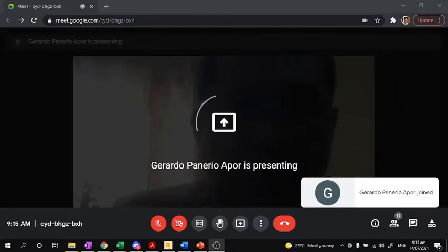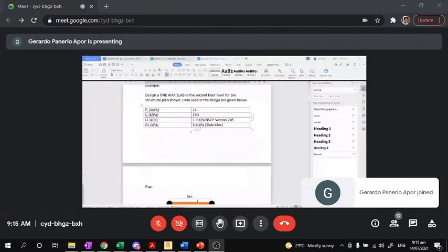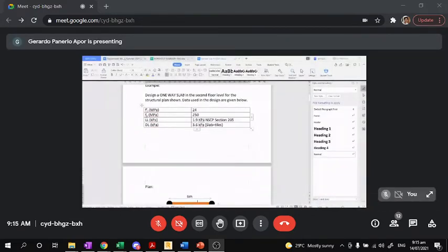In this plan that we are going to design, the live load is 1.9 kilopascal. Remember, kilopascal, so it should be per area. The dead load is the weight of the floor, which we assume to be 5 inches, plus the thin tiles. So, it is 3.6 kilopascal.